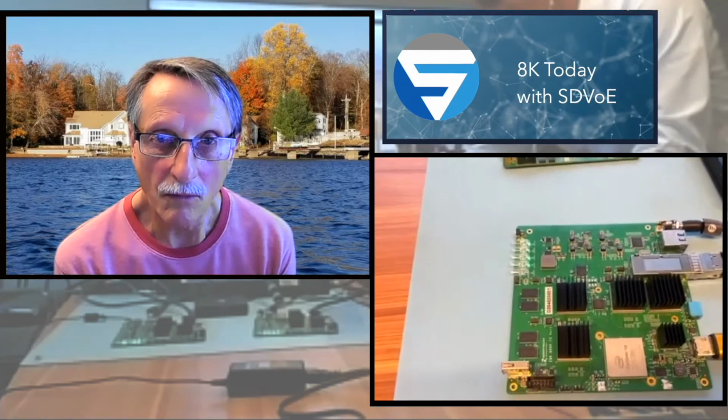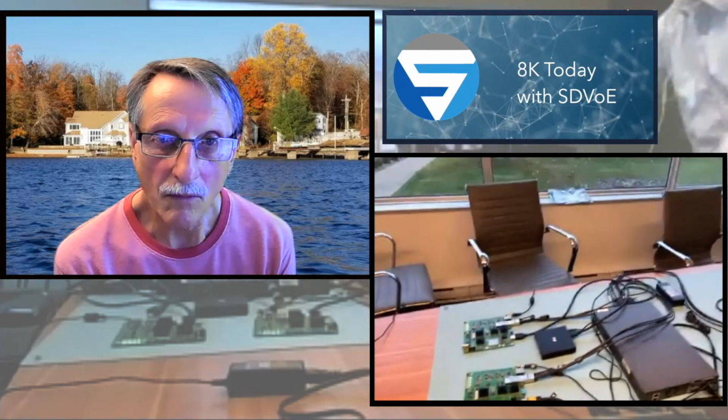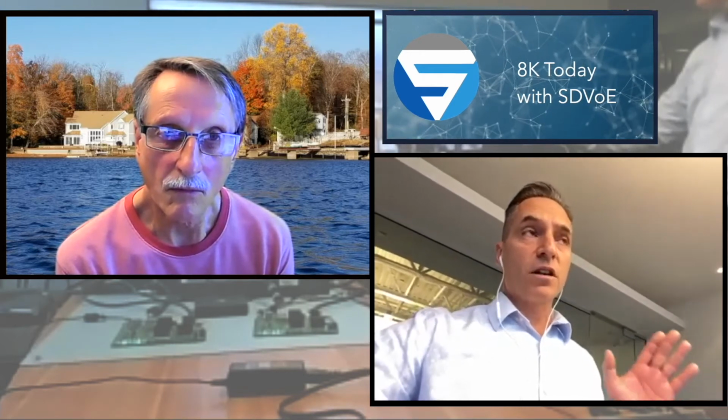And the reason is we can have a little FPGA, very cost-effective FPGA in front to split the signal in a by 4 fashion. So we take this 40 gigabit and the very first piece of logic that signal is going to hit is an FPGA that will then create 4 10 gigabit right out of this 40 gigabit.